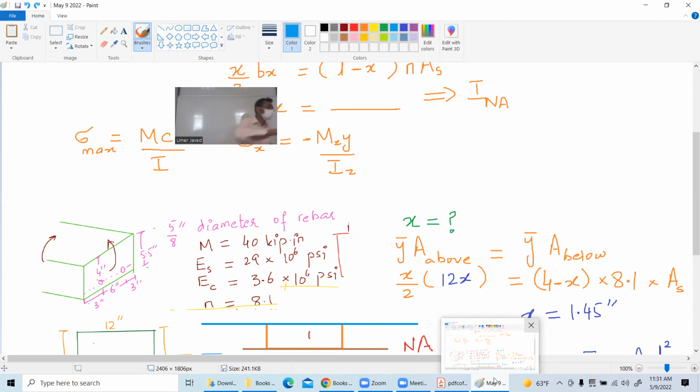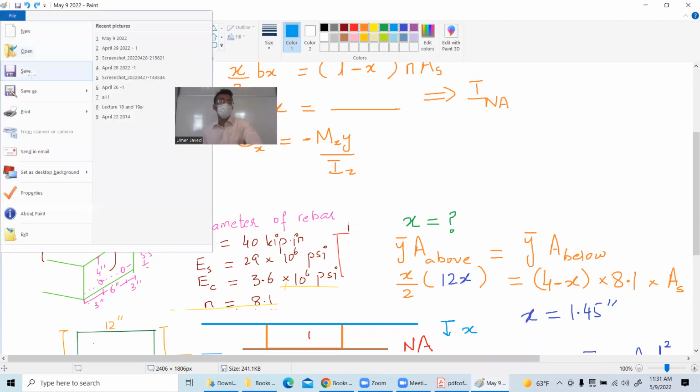Yes, it's a good question: why aren't we talking about the maximum distance from the neutral axis all the way up to the surface? Its maximum distance is up to the surface. But for this surface it makes sense, and for this surface it doesn't. Actually, this is compression, this is tension. Concrete is not good in tension, and we have put the rebar, so we want to see how much the rebar is holding. Okay, I get it now. It's a good question.